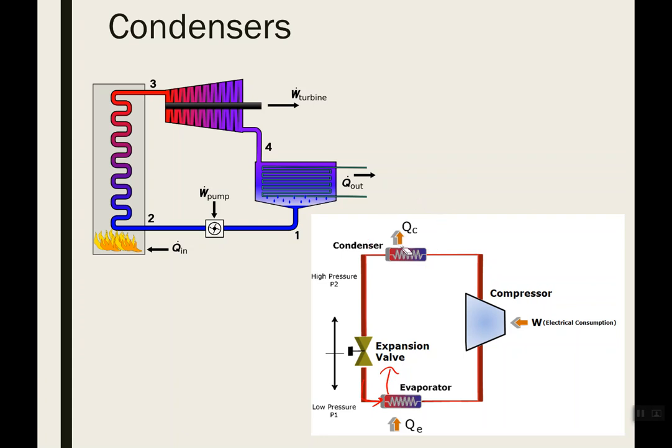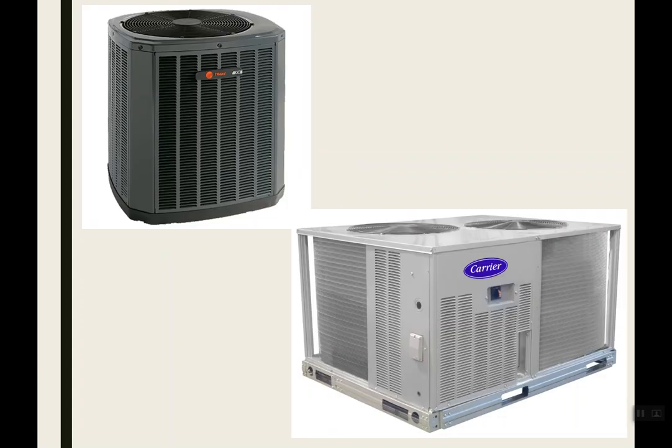So the condenser is condensing your refrigerant back down before you can run it through an expansion valve and start the cycle again. So this is what your compressor/condenser looks like. All around the outside of this, if you looked carefully through those little slits, you're going to see little tubes that are circled about with little aluminum fins, and there's just a ton of surface area that happens there. But the whole objective of the condenser part of this is to condense your refrigerant back down.